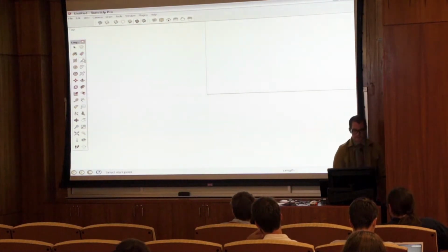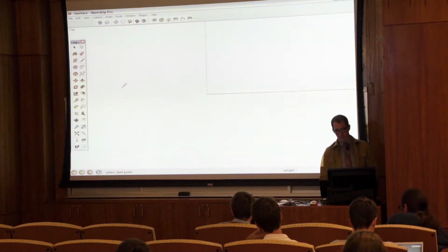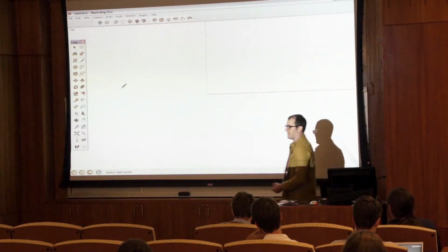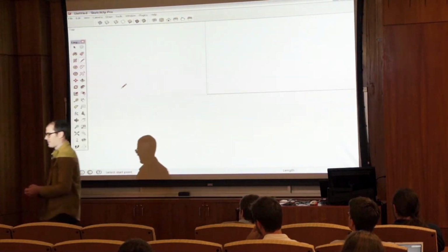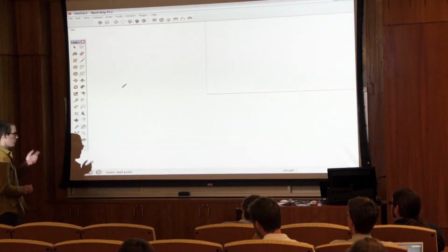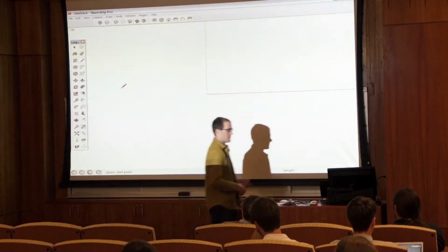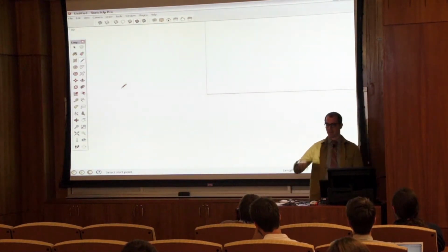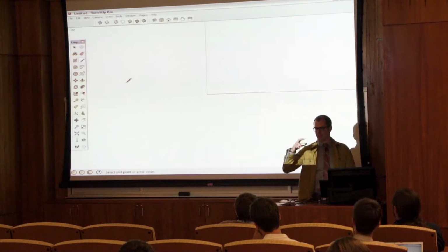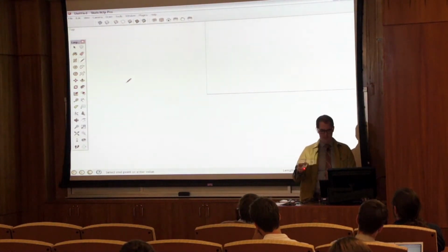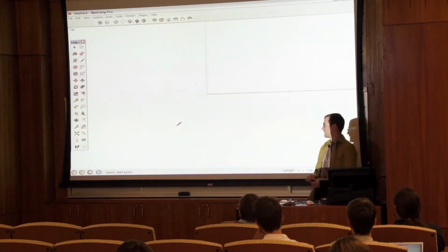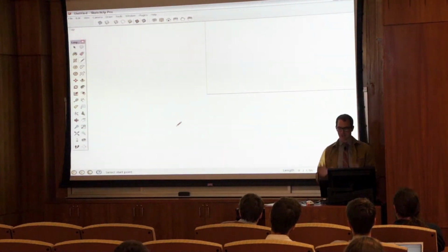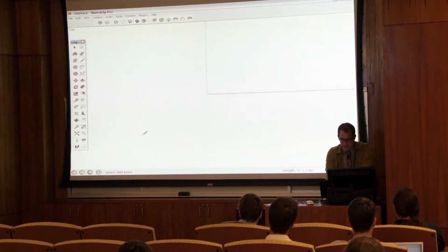So let's get started with the line tool. It's also L as a keyboard shortcut. And although we can't really make this mistake because most of us don't have a mouse right now, one important note that I want to make about SketchUp: SketchUp is a click and release tool. So what I mean by that is you're clicking and releasing, not click and holding, to activate any tools. It sounds really silly and simple, but rest assured, please just keep in mind SketchUp's always click and release. It'll make a lot of the tools later on in SketchUp a lot easier to use.